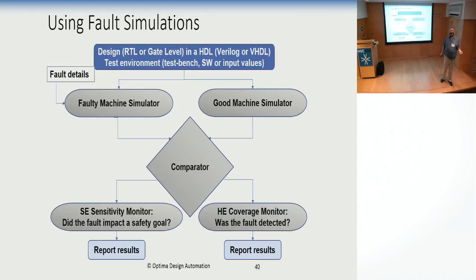There is some research now to identify if for soft errors 1 bit flip is enough, or maybe we need to do 2 bit flips of adjacent nodes, because the phenomena of an external radiation can sometimes throw enough electrons and holes around to hit 2 flops in very close proximity and change them both.